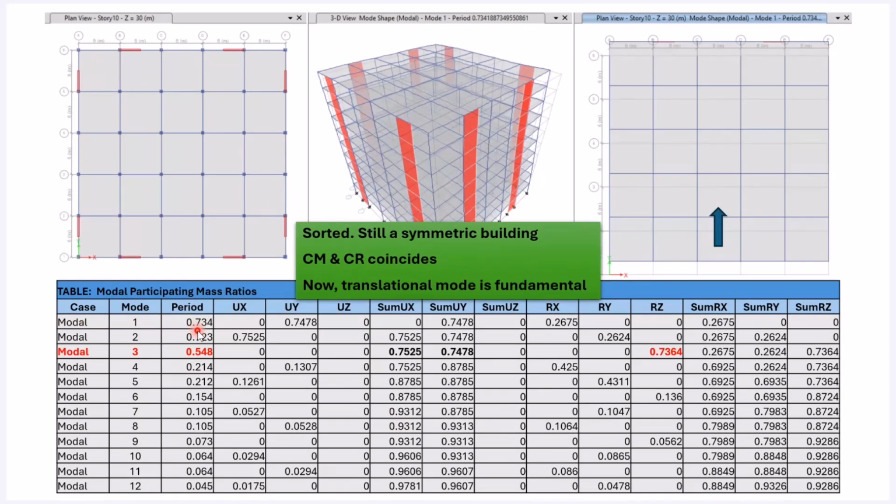I've modified this structure. This is a modified model, but using the same quantity of shear walls. So it is 6 plus 6 in each direction, so a total of 12 meters, and that is distributed in these locations. So moving away from the center of rigidity for the walls, primarily the walls are going to give a significant amount of lateral stiffness for the frames compared to the columns.